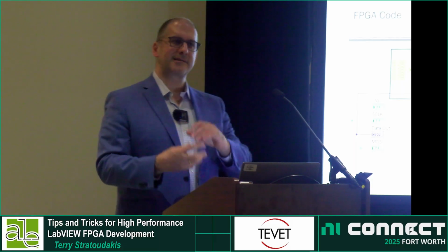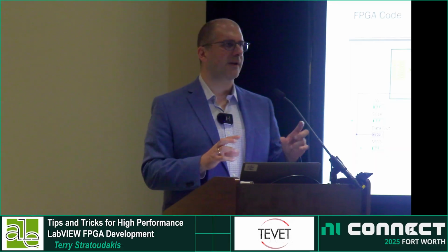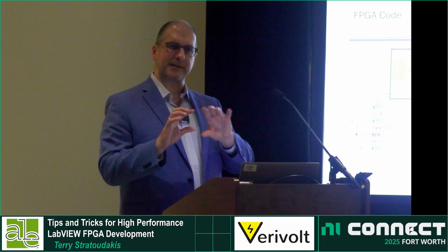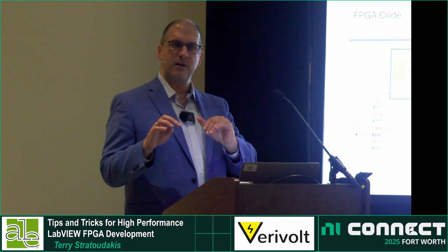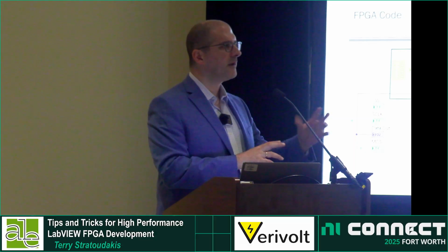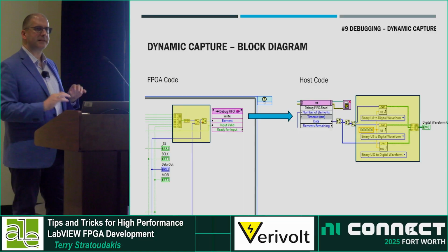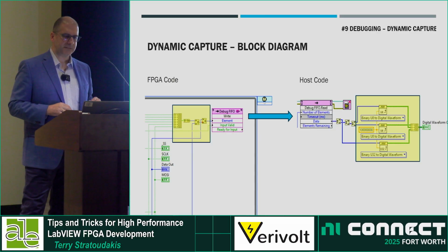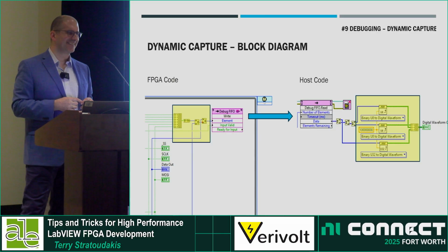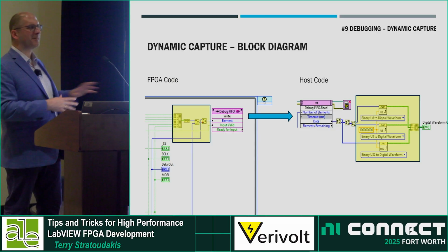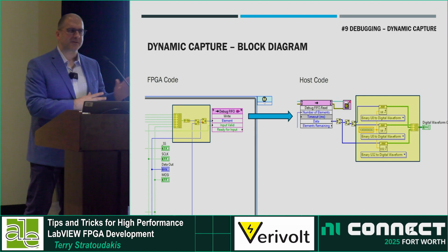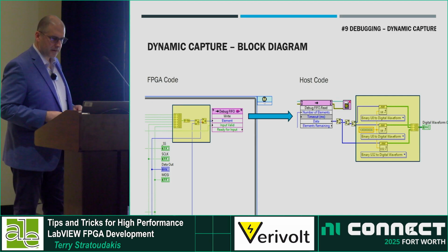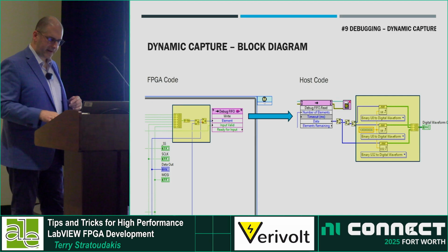And the DRAM has, I don't have that as a tip here, but it has a configuration where you can have it set up as a FIFO. So you configure it as a FIFO, so the interface into this is not all that different. You don't have to manage addresses. And there's an example for that, by the way. Remember, tip 1. Tip 1 should be like 10 tips, but that's the tip. All of these things are related.